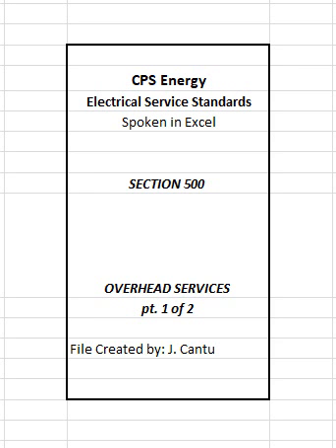504 Length. The maximum length of unsupported service drop conductors is determined by CPS Energy based on the wire size, weight, sag, and tension on the anchor points. Service drop conductors greater than 1/0 AWG may require the use of one or more clearance poles for support. Demand load may limit service drop conductor length due to voltage drop limitations specified by CPS Energy, refer to Section 300.